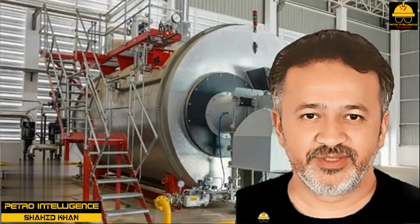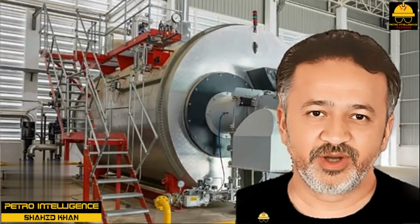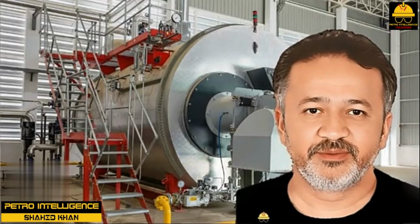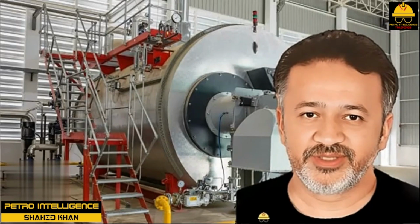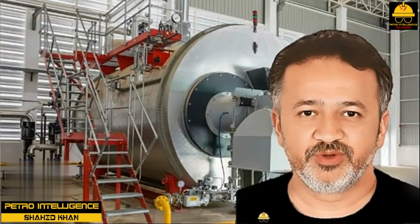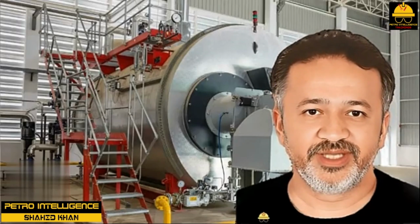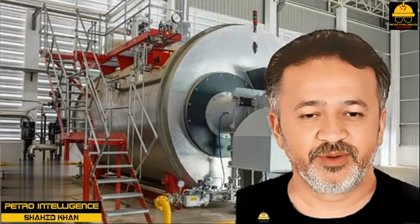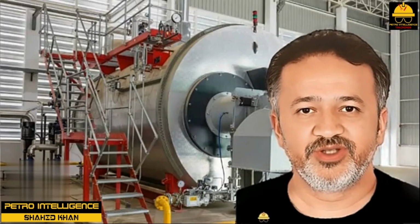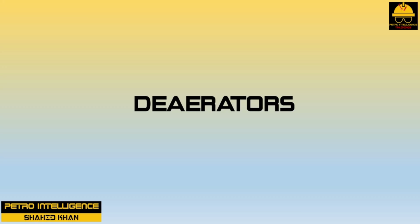Depending on the contaminant, the condensate may be reused for a number of services. Our favorite reuse of such contaminated condensate is as a replacement for velocity steam in the heater tube passes of a fired furnace. There is little danger in injecting a controlled amount of water into a furnace inlet when using a properly designed metering pump. Such pumps typically have a capacity of 1 to 10 GPM and provide a set flow regardless of the discharge pressure. The injected water flashes immediately to steam inside the furnace tubes.